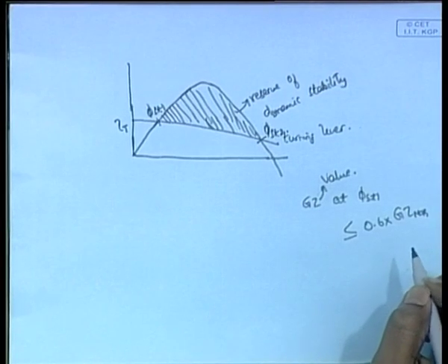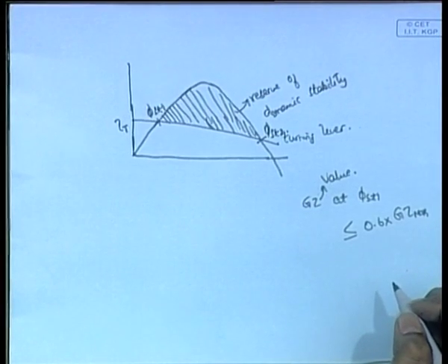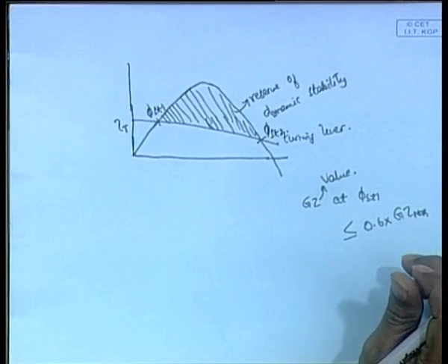So, whatever is the GZ maximum, that is the maximum righting arm for that particular ship, for that particular GZ curve of that ship. Note that every ship, once it is defined, will have its own GZ curve, and once you define the GZ curve of a ship, you find out the maximum GZ that will happen somewhere around the middle, usually from 0 to about 70 degrees, it will be around 40 degrees probably.